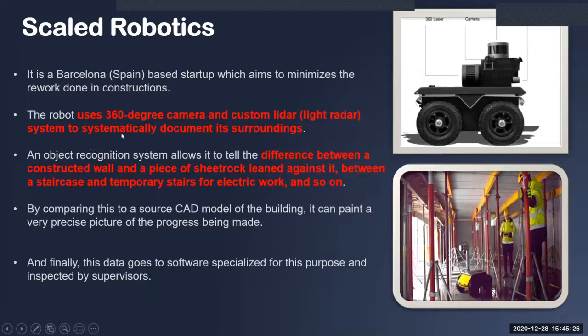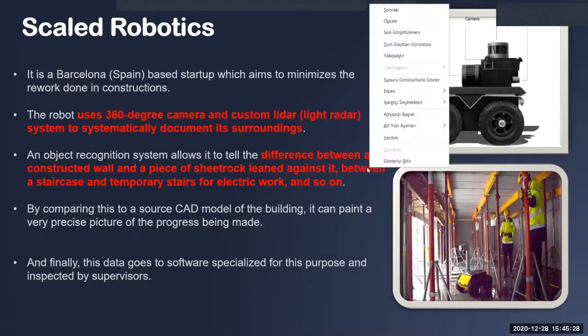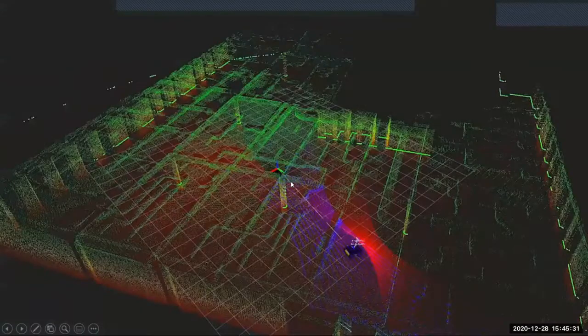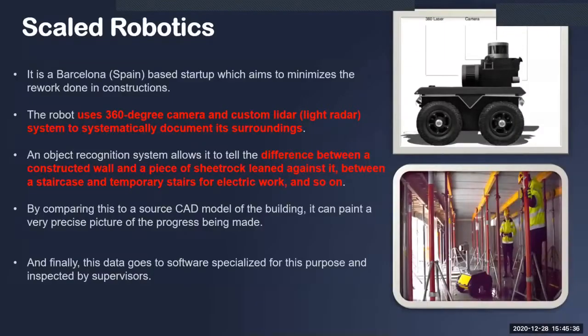This robot has cameras and lidar on it, as you can see in this presentation. It's a lidar representation of the robot. This robot collects data with its cameras and lidar, and it gives a model of the construction. It can also be used as autopiloted or controlled, as a hybrid, as Caner mentioned. And it allows determining faults in the constructions with its visual interface, which is supervised by a professional.